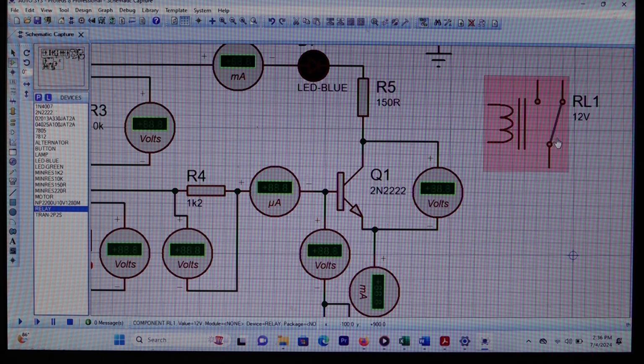So we can also verify one of the mathematical equations that we learned in load line. We learned that for the output of the bipolar junction transistor, we always have a mathematical equation. When the emitter is grounded, VCC is equal to collector current times collector resistor plus VCE.